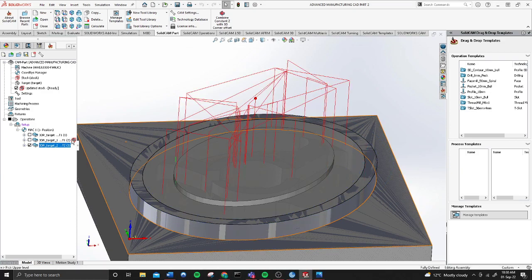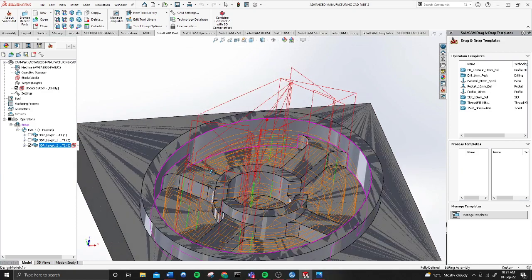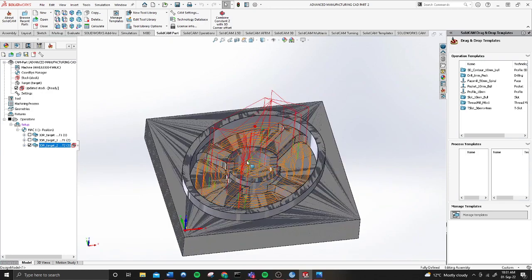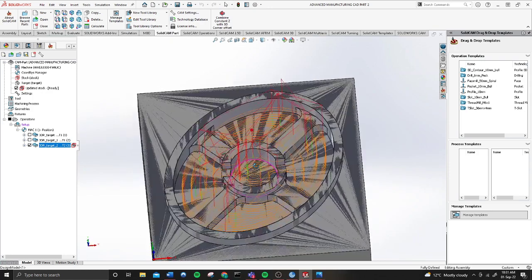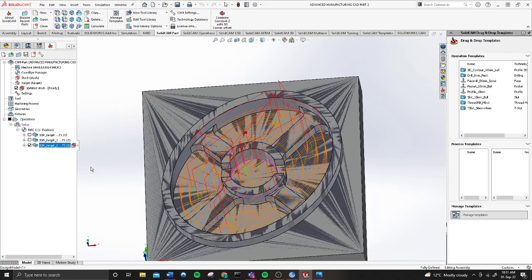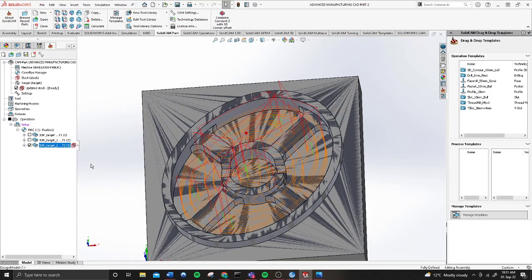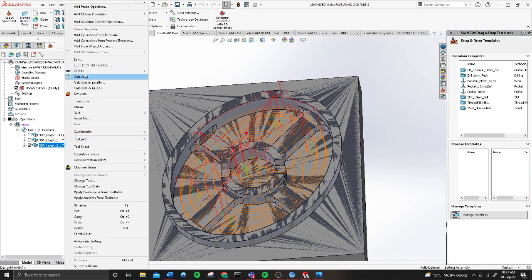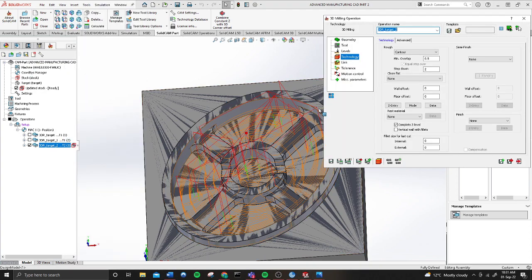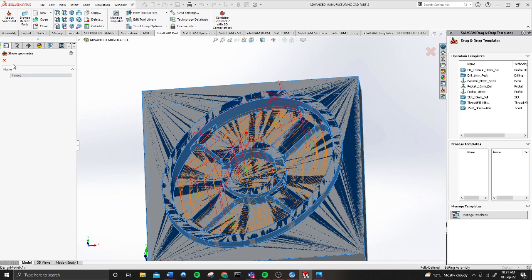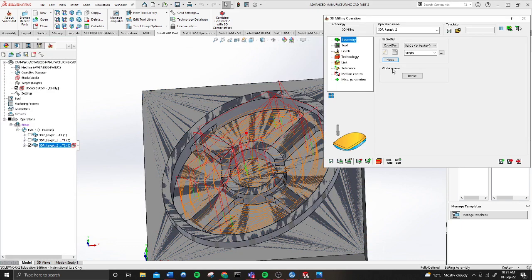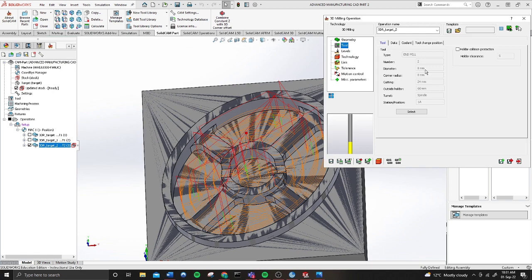And then for the final pass, it's basically a bunch of plunge cuts as well as the contouring operation. It's a pretty complicated pass, but it's going to hollow out all of the internals as well as get all of the geometries. And so it's a 3D milling operation. It's basically just selecting the inside of the face to machine out. The tool we're using is the 8mm.